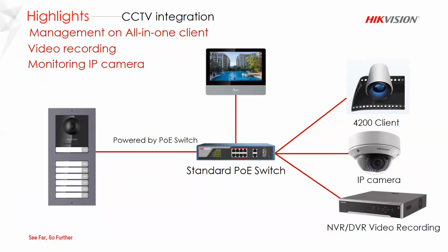Okay, and then all the CCTV integration is included, including these cameras. All the IP cameras can be added to the indoor station, so you can view up to 16 cameras on the indoor station. Not at the same time, but we can add 16 cameras on there. And then this camera on the door station can be viewed on the recorders as well. So it can be 24/7 live view and the recording, including audio. Okay, and of course, every Hikvision product can be managed by our iVMS-4200 or Hik-Central Pro.